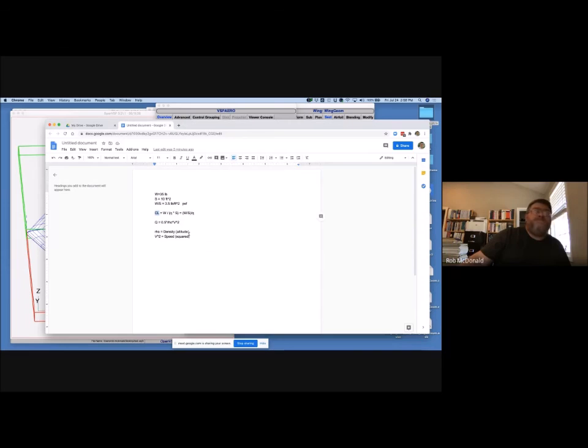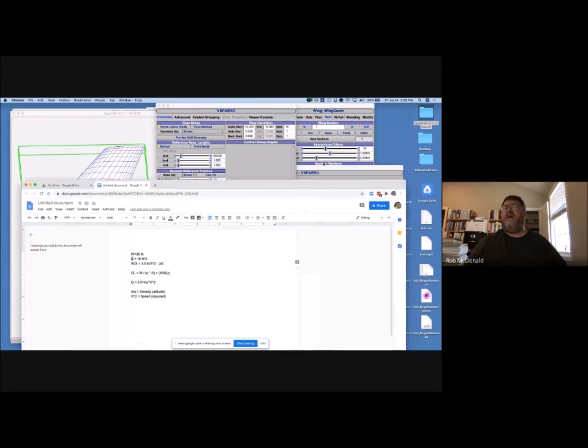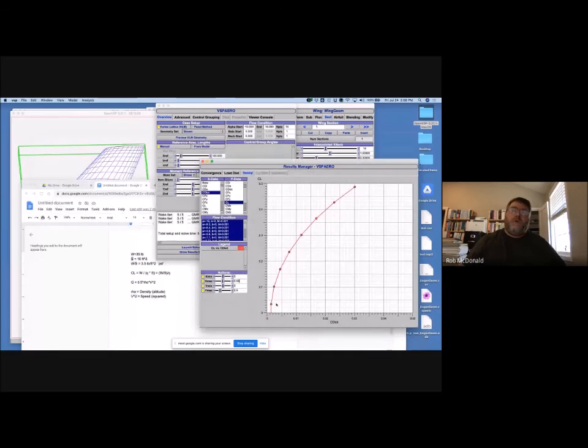And that's by trimming the airplane. As an engineer, I can change W and I can change S, right? As an engineer who's designing an airplane that doesn't exist yet, I can change those variables. And what we're trying to do, remember when we looked at our drag polar, is figure out, let's say we want to fly at the best L over D speed. Notice that tangent point that I'm talking about, it occurs at one very particular CL.